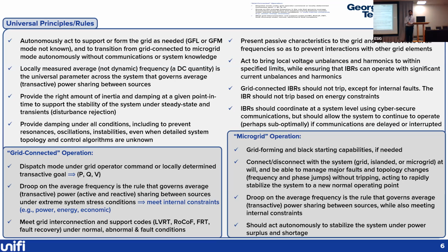It should be able to provide unbalanced current. It should be able to mitigate harmonics in the network. This may be a little bit more crucial for distribution system connected resources, especially if there are many single phase inverters present and you have a 3-phase grid forming inverter present. So the grid forming inverter in a way should act like an active device, which is going towards trying to mitigate the imbalance and mitigate harmonic injection in the system.